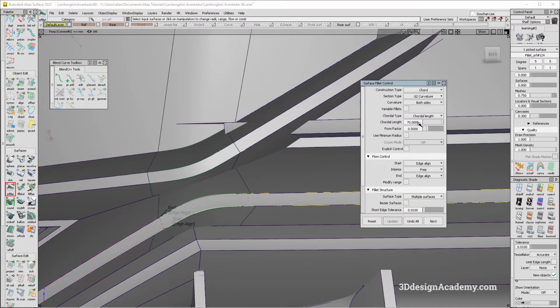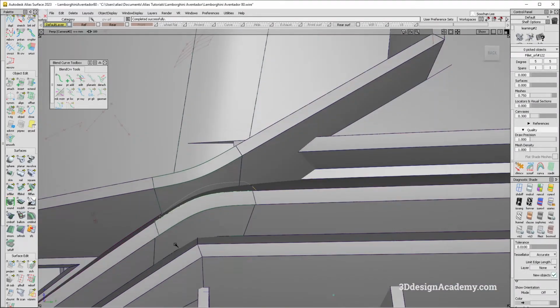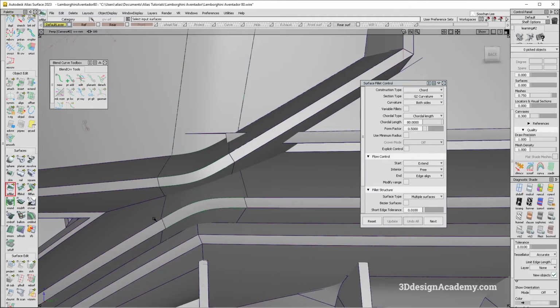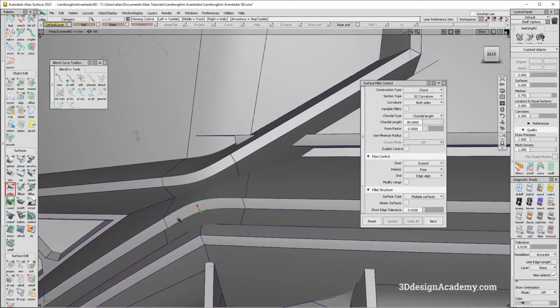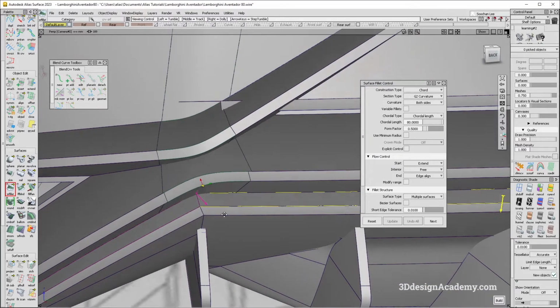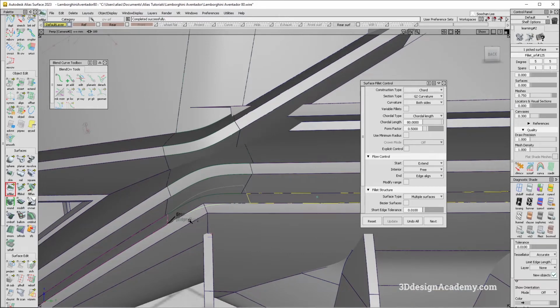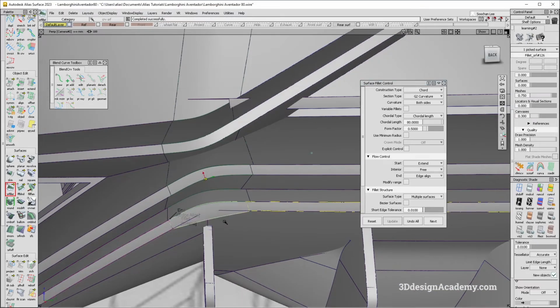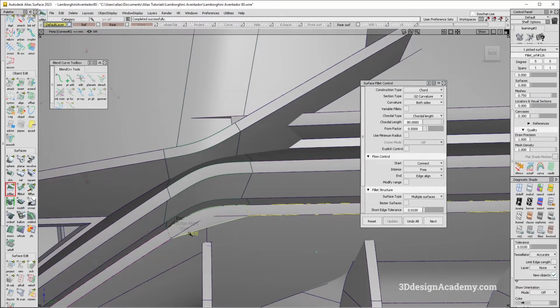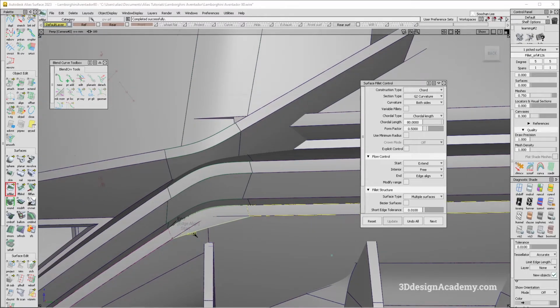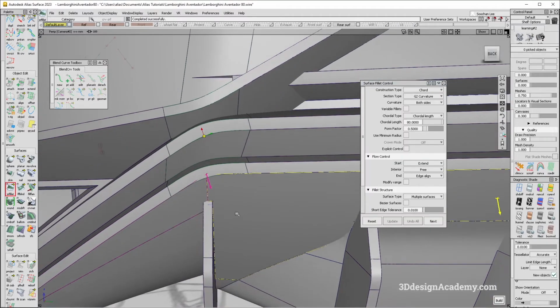So let's go ahead and do that. Maybe 80 over here, 80 over here. And this one, I think I can just leave. Now this, the primary, I guess the driver for the fillet size is probably this one. And actually, let's go ahead and do these ones also. So I'm just going to do 80 for now. Let's see if this one works. Yep, it does. Edge align.